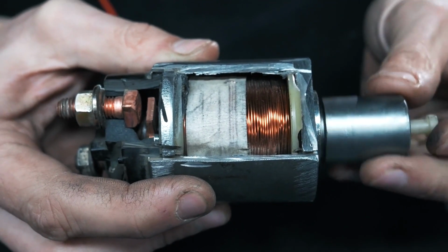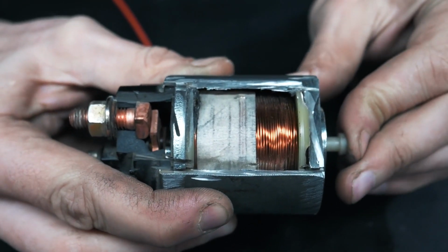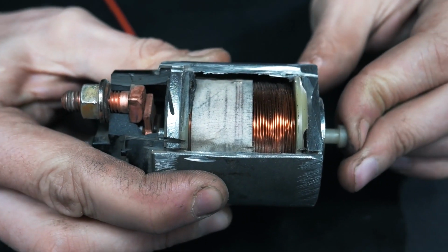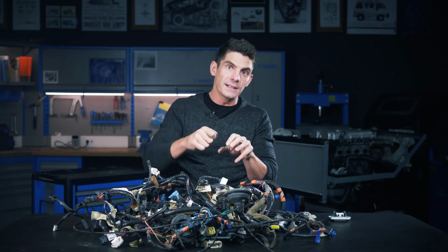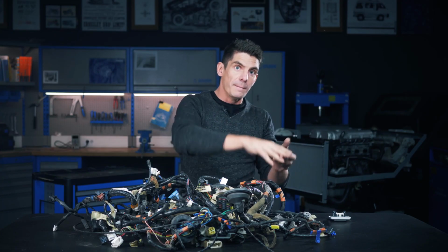And if you think back to when we talked about the starter motor and we looked at the solenoid there, the solenoid is really just a king size relay. It does exactly the same job. A small current from the ignition key is used to turn on a massive current from the battery over to the starter motor. So switching big currents directly requires big switches, and they're heavy and they're relatively expensive.